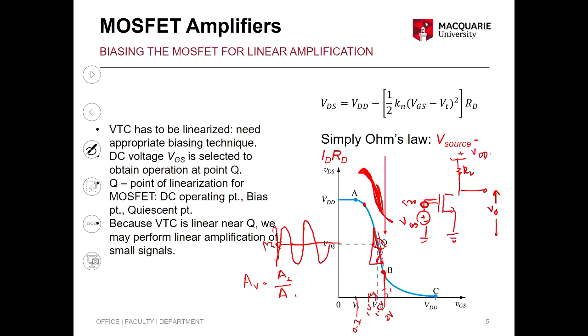In your receiving part, you have a low noise amplifier. That doesn't have to be high gain. It can be a certain gain. You can have multiple stages, but it can use less current. So you bias it lower. So that's the takeaway from this. That's what I want to give you. You may have learned this, but that's how you apply it when you design the circuit.